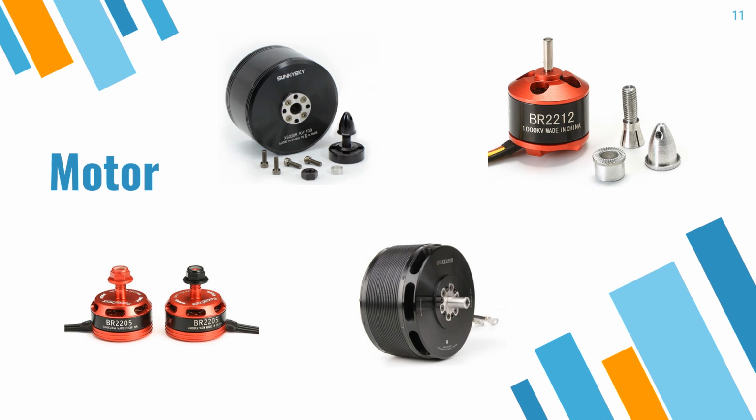The first thing to consider when choosing a motor for your application is of course the amount of thrust it can provide, or the amount of weight it can lift. But besides that, there are two more important parameters to consider. The first one is how efficient is this motor? So how much power does it drain from the battery in order to provide the amount of thrust it has? And secondly, what's the kV number of the motor? kV stands for RPM, rotations per minute, per voltage applied to it. So it basically is a measure of how fast the motors can spin.